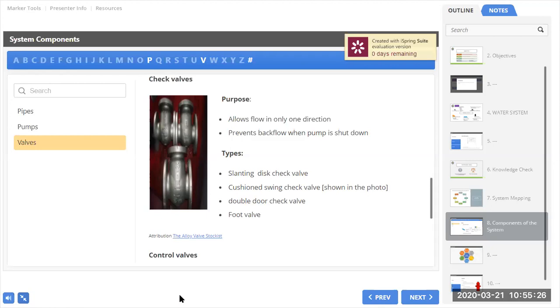A cross connection is a connection between the water system, our water distribution system, and a system that is independent. It could be an industrial place where they have tanks that have water. Sometimes in these industrial places, these tanks are also connected to other places, maybe pipes where chemicals are flowing.